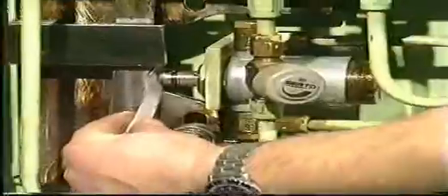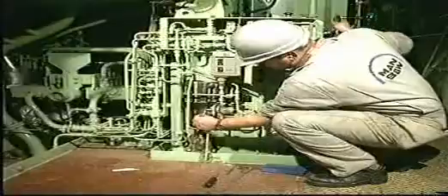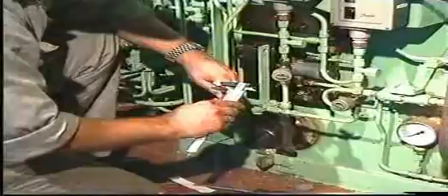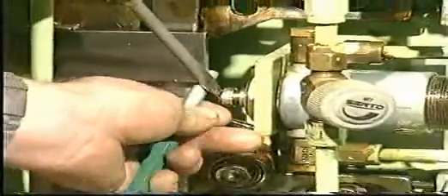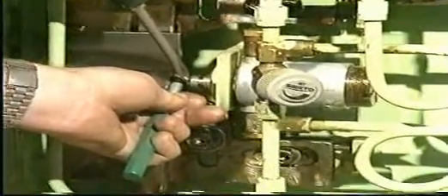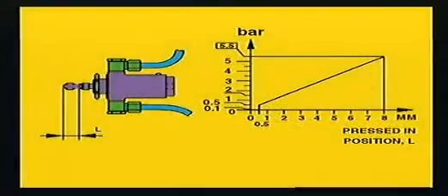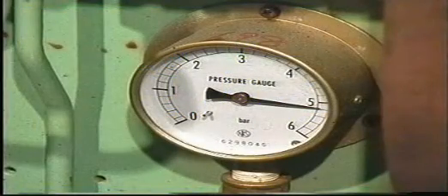Turn the regulating hand wheel so that the steel bar just touches the pilot valve. Insert a distance piece with a thickness of precisely 8 millimeters. If the control air pressure deviates from 5.5 bar, loosen the lock screw and turn the spring retainer cap of the pilot valve until the pressure, which can be read on the pressure gauge on the engine side control console, reads 5.5 bar.